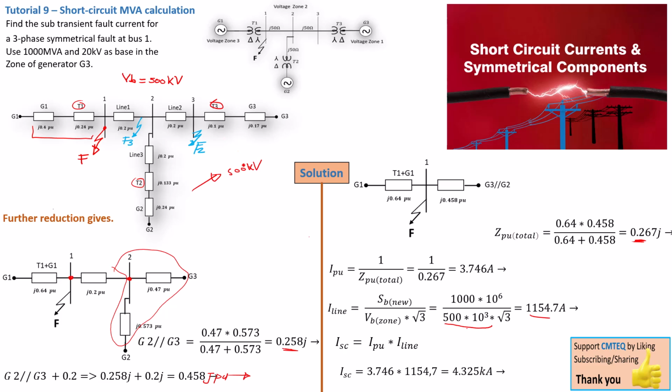All of these are going to give you different values of current, because wherever you place your fault, you're going to have a different value of impedance, as these sources supply the current. They all try to follow through to where the fault is. So already the impedance value changes, and that dictates what the per unit value will be and what the short circuit current will be at that point.